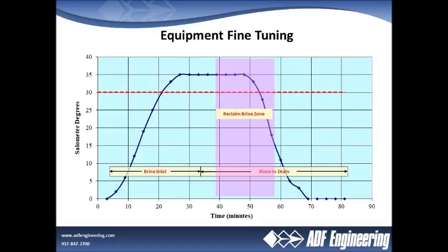And then the next step is, this is again a continuation of softener regeneration. You would recognize this as what we call an elution curve. Basically you do this to make sure that what we call the 30-30 rule is met: for at least 30 minutes you have brine with 30 Baumé degrees in contact to get efficient regeneration of your sodium cycle resin.